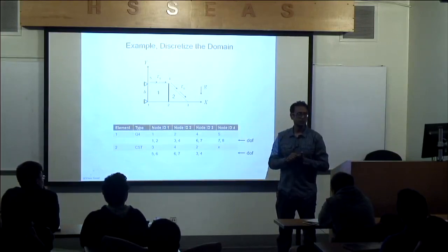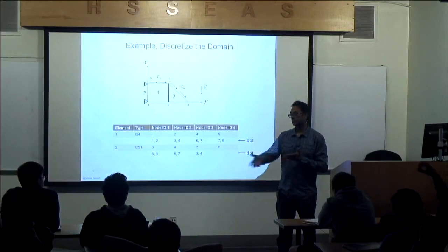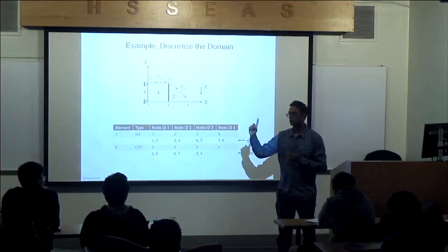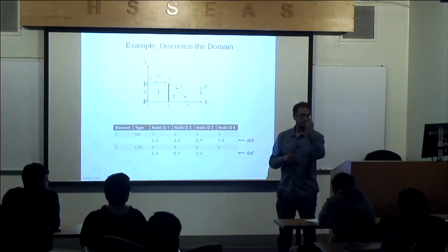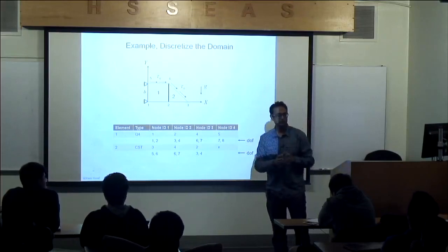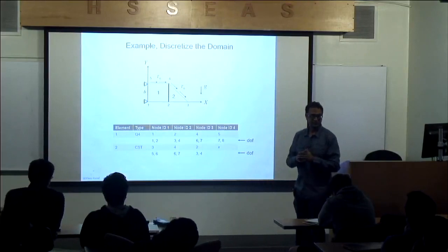Do we need to use isoparametric? If I was you, I'd use isoparametric because it will simplify all the calculations. You can just use one shape function for everything. The Jacobians will look different. Now you understand why I did two elements and not three.